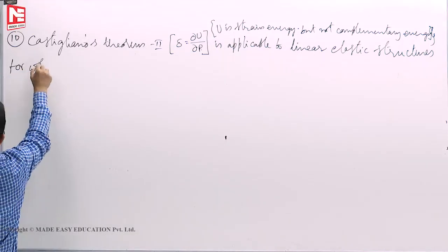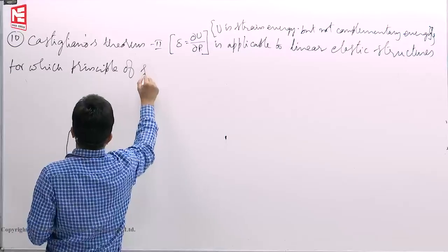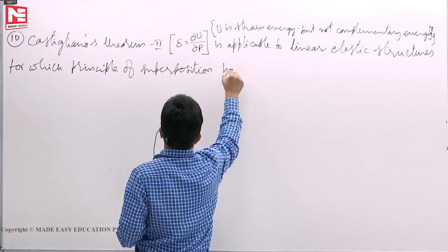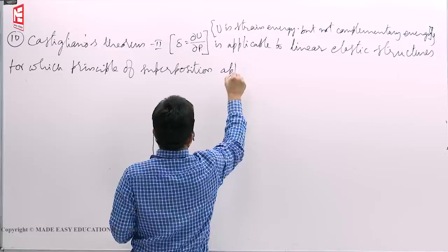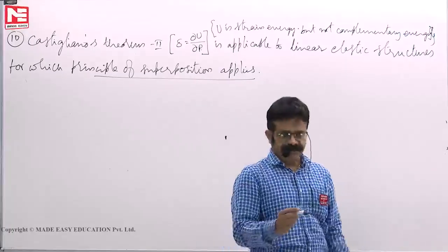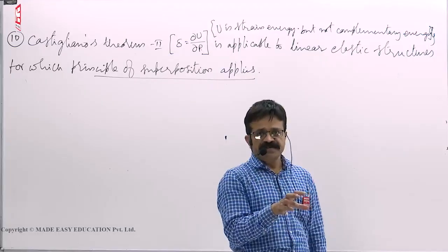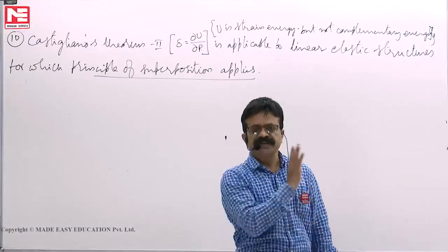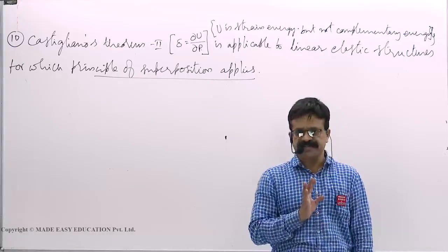It is applicable to linear elastic structures for which the principle of superposition applies. Just because you have a material which is linear elastic, if large deformations are there, you cannot apply the principle of superposition because geometric nonlinearities will exist.